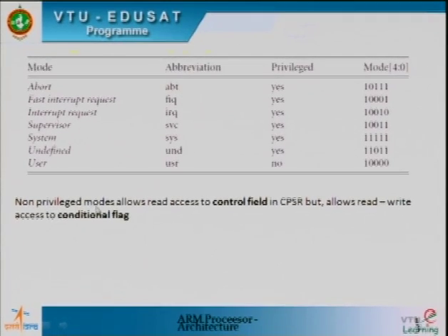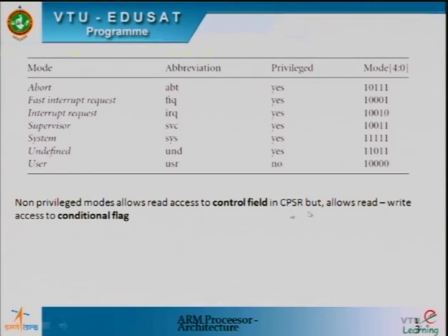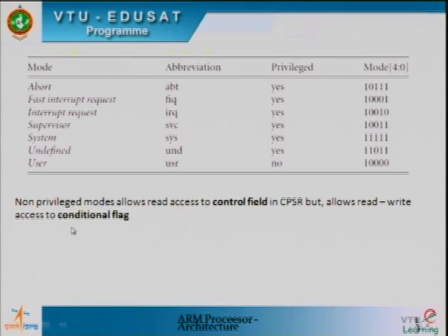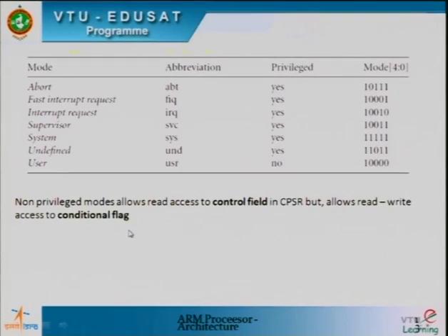So non-privileged mode allows read access to the control field in CPSR, but allows read write access to the conditional flag bits, or the flag bits, right. So when you select conditional flags, they indicate the nature of the result of an operation.